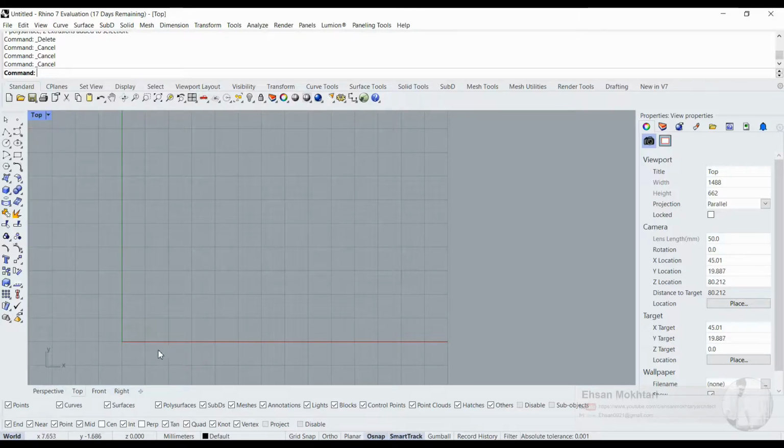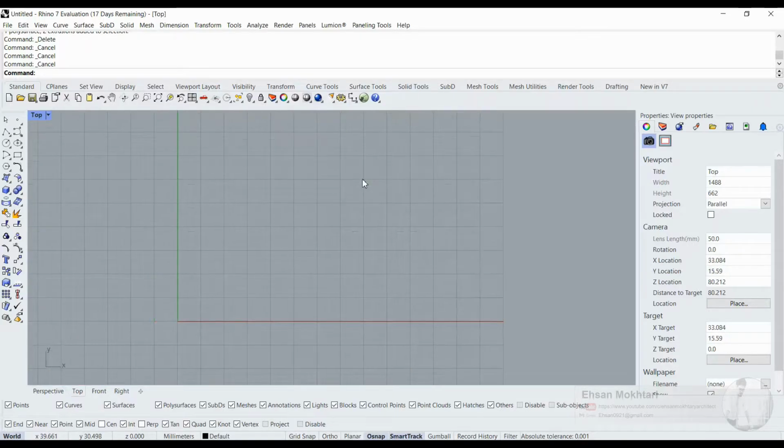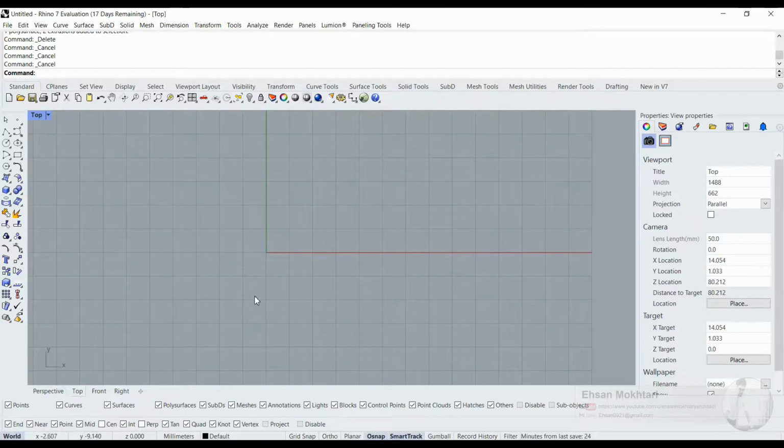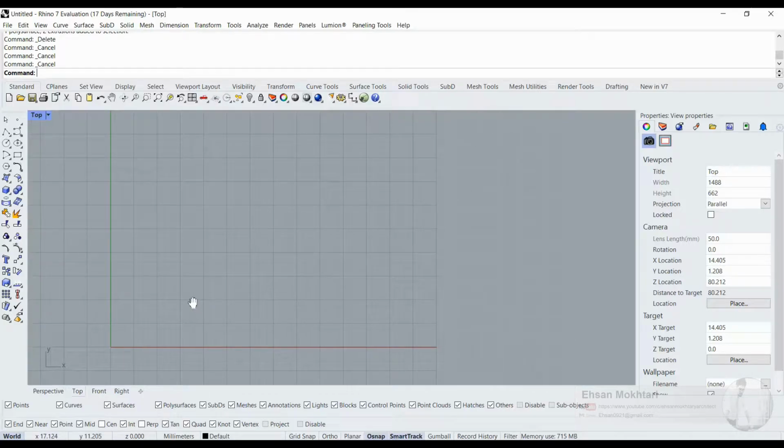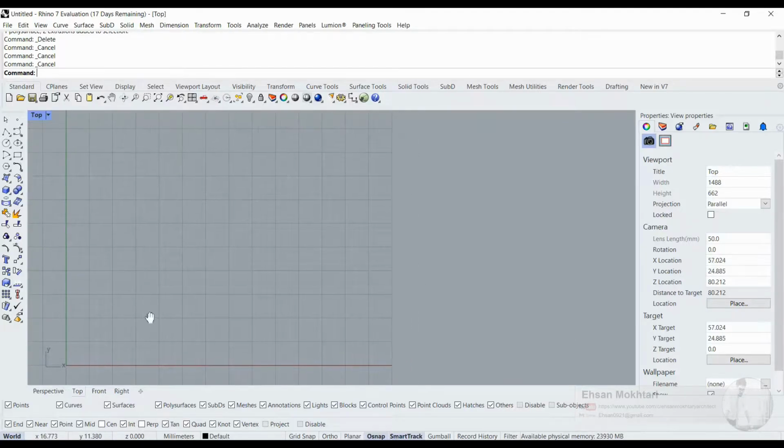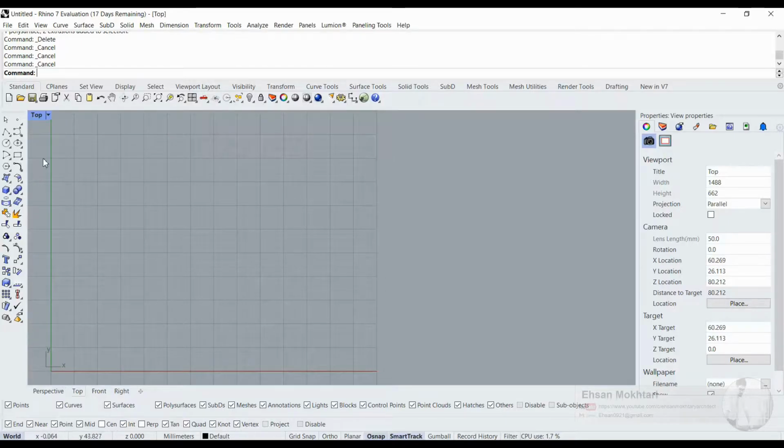And this solid line here shows our 0, 0 coordinate point, meaning that here is negative x and here is negative y. So if you work here, it's mostly positive points. We try to work mostly in the positive area, but if you work in the negative area, mostly it doesn't matter, unless you are working with coordinate points. So here I'm going to create a line, and we are going to create a box or a rectangle, for example, 5 by 10.